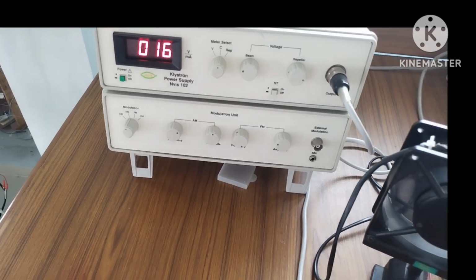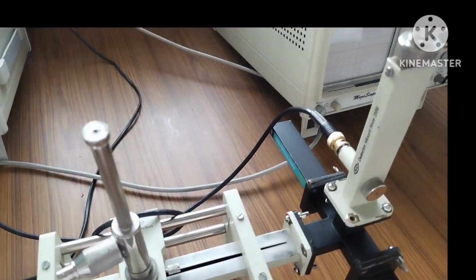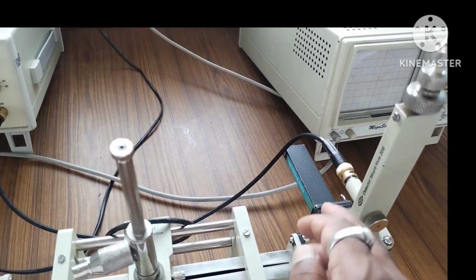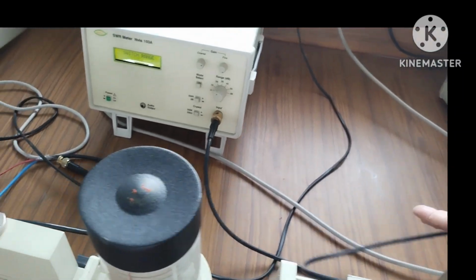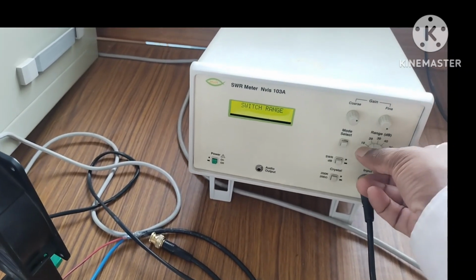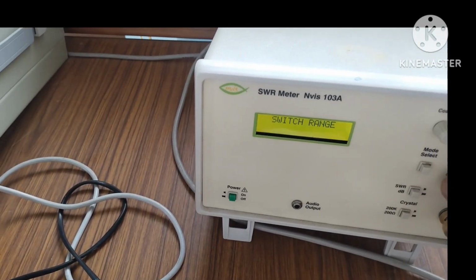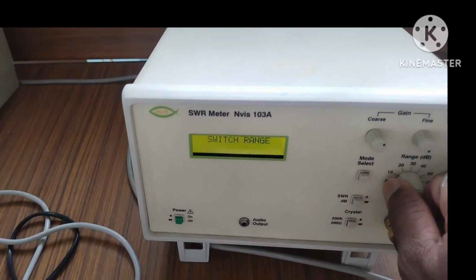After the HT is on, this port 4 has the detector mount. This detector mount is connected to the VSWR meter. So here the range is required. You can move this range. The previous range is not sufficient, so now we can change this range.